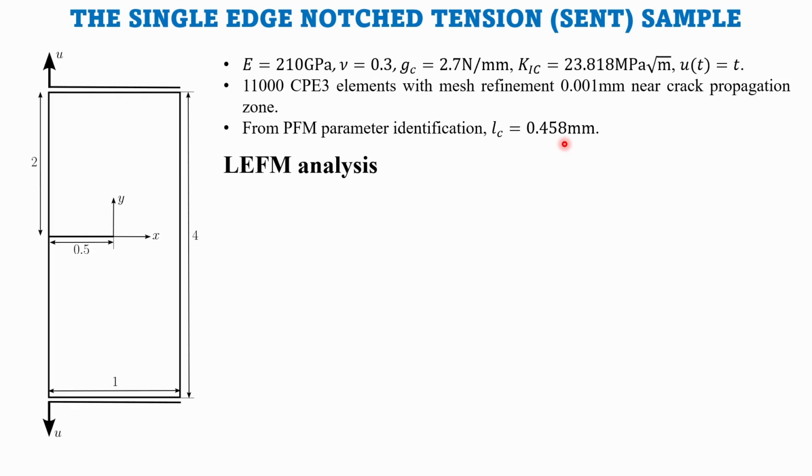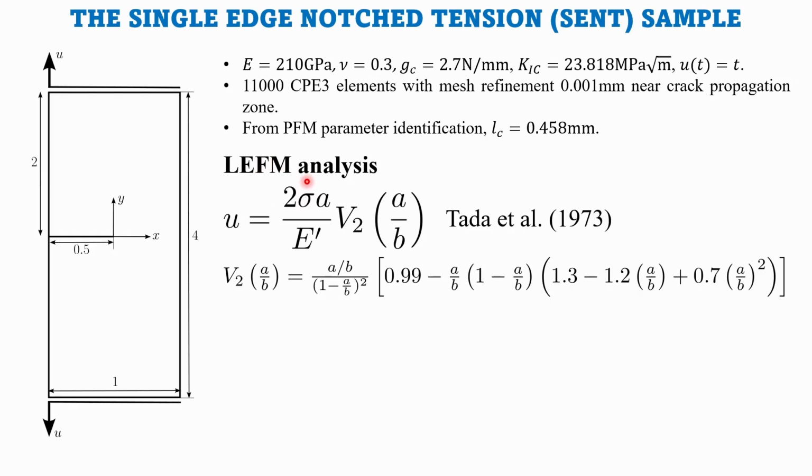Now we first look at the basic LEFM analysis. From this paper by Tada, he gives a relation between the displacement formulation and the stress formulation, because this is a displacement formulation. The expression for your stress intensity factor is always sigma root pi a times some function due to geometry. Again, recap your fracture mechanics, because that is what I'm talking about here.